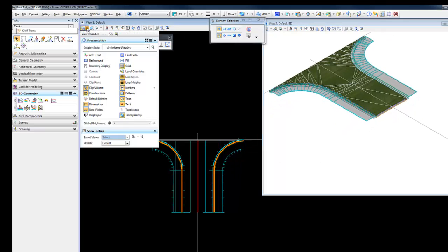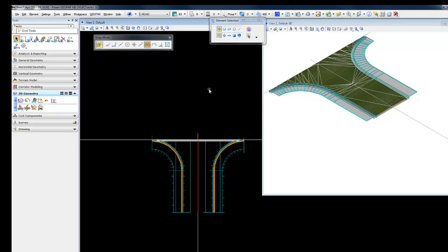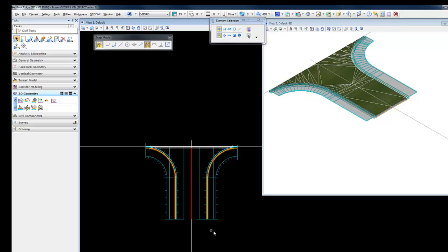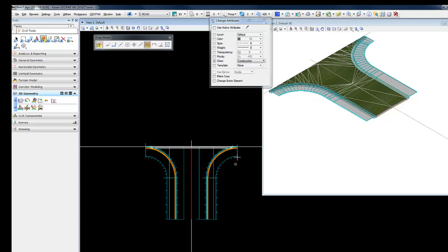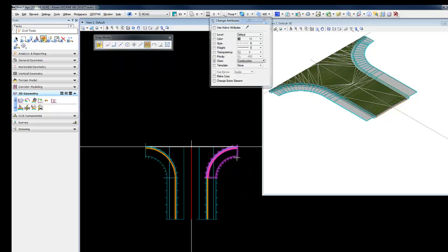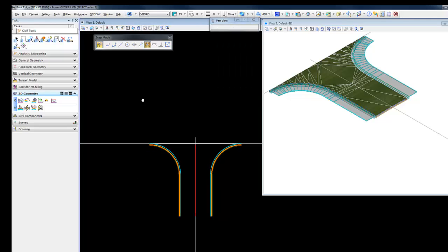Some other things we can do to dress up the cosmetics of the cell is we can set things as construction classes. As you've seen, we put one element in a construction class already. We can further this by getting rid of some of these constructions for our linear templates by hiding them in this construction class. So we'll just simply turn the constructions off, and move through our cell and add the elements to that construction class. Now we're ready to create the cell.